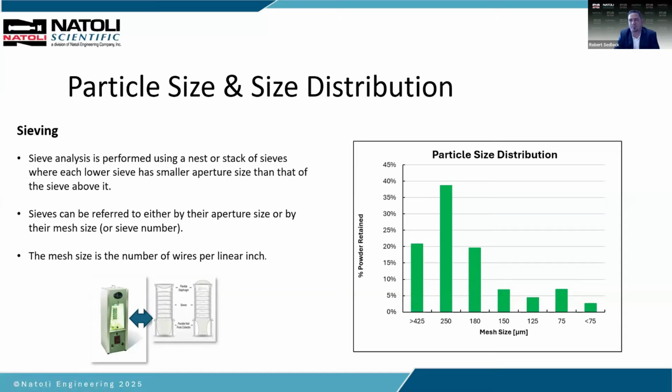That material flows better. When we get below 0.2 grams per ml, that material's fluffy, and we're probably going to have some issues with flowability and getting those particles into the die cavity at high speed manufacturing. So bulk densities above 0.2, 0.25 grams per ml is where we want to be.